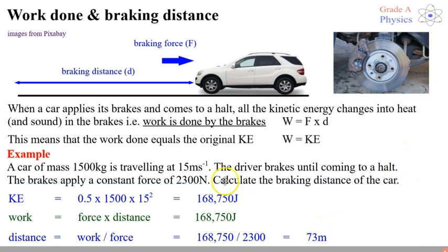It sounds about right. That's relatively fast. It's quite a heavy car, 73 meters. Okay, well, that doesn't necessarily mean the emergency braking distance, but with this applied force, then this is how long it will take. So we can use this approach for not just braking cars, but for any object which is slowing down and converting its kinetic energy into heat energy. So very, very important you practice that.